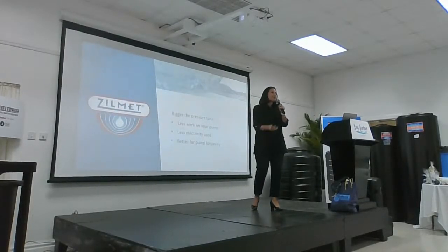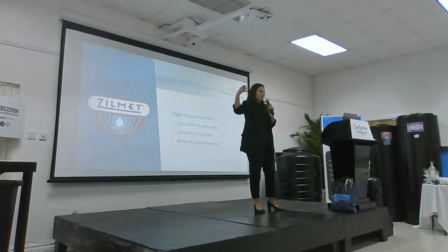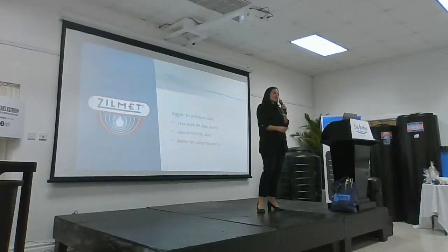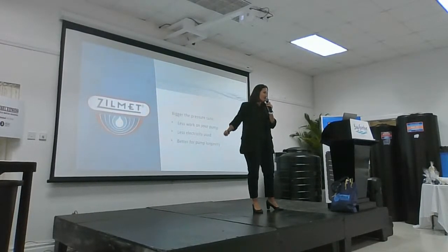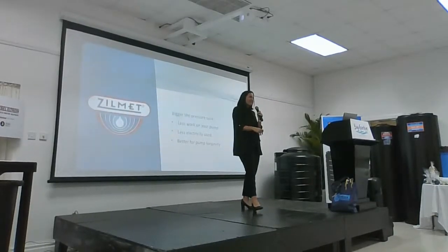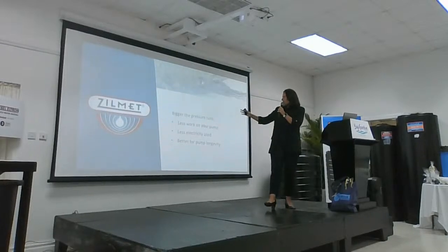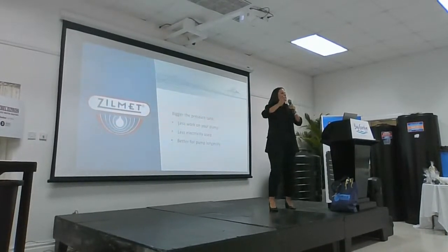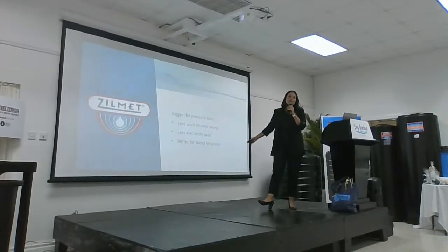So think about it, an analogy. Driving down the John Compton Highway versus driving through the windy roads of Superior. Your car and your motor are going to run far more efficiently on the John Compton Highway when there's no traffic, versus the winding roads of Superior. So similar to the pump, the bigger the pressure tank is, the more efficiently it's going to run, because it gets to run at longer periods with less variation. So it's better for your pump's longevity.